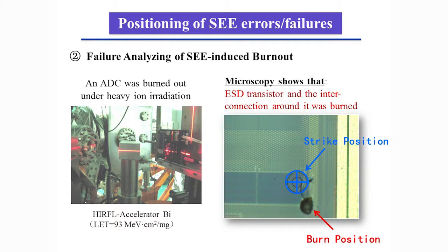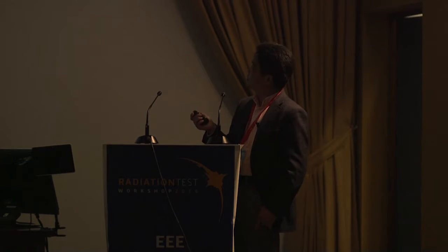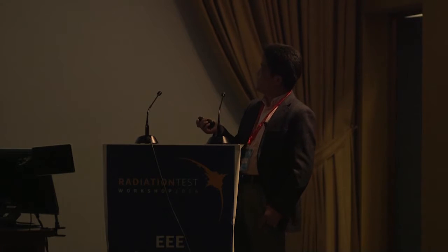The second example is to do further analysis of SEU induced latchup. Here is the ADC. We did the experiment and we found the ADC with latchup under heavy ion irradiation. Here is the microscope image. We find the ESD transistor and the interconnection around it burned.